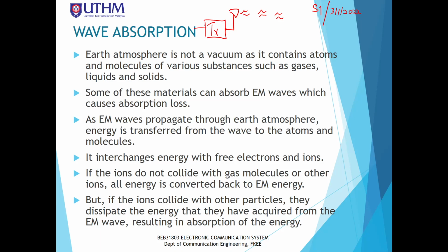Okay, so attenuation that we have learned previously is, number one, due to the distance. Another one is due to the absorption. Absorption by many things, some of the elements in the medium, for example, water molecules, the air particles, gases, rain, even trees, buildings, and so on.